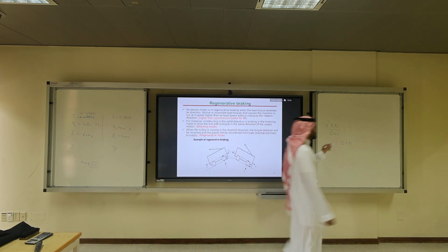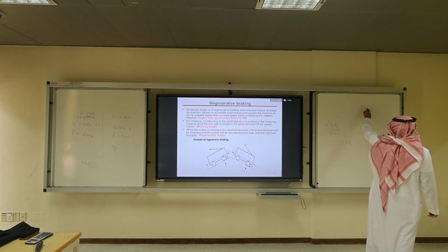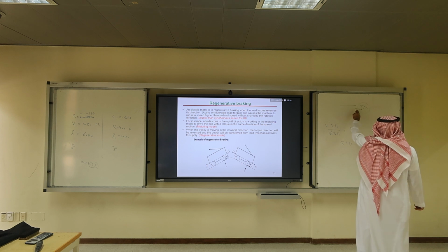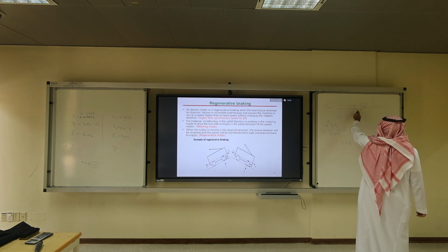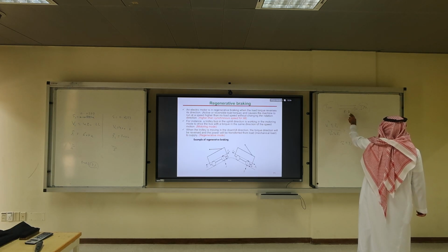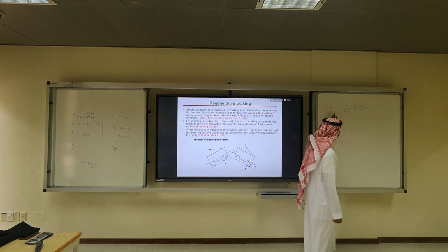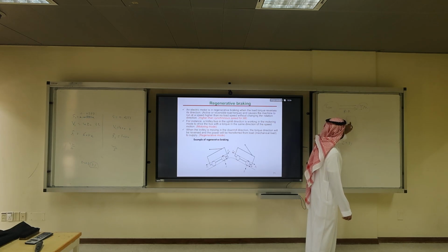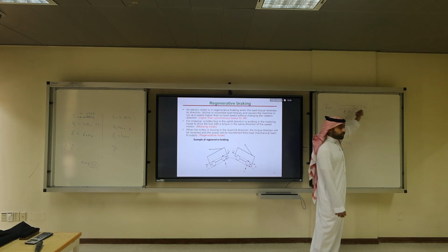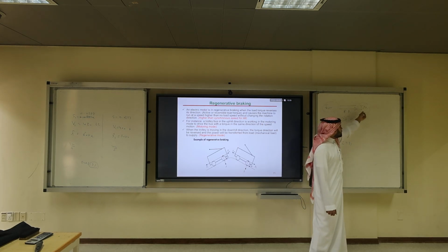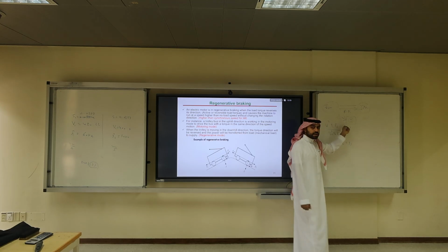Regenerative braking means in your car you will find the flow of energy goes from the tires to the IM. This is regenerative braking. Okay? Or it goes to the battery. In regenerative braking, the load, which is the tires, sends energy from the tires to the induction machine or to the battery.